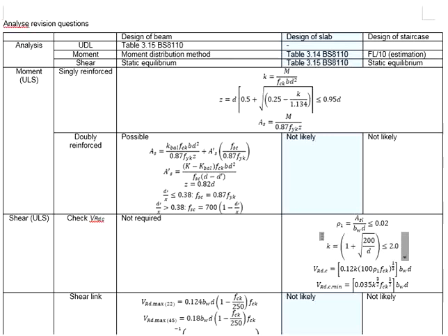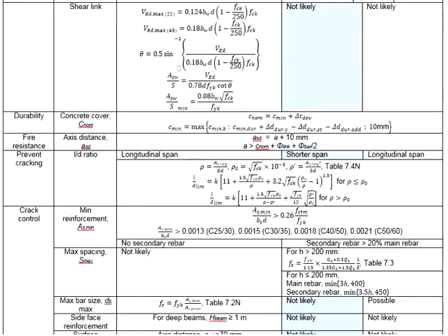Even there is no moment for the longer span of one-way slab and for the transverse directions of the staircase, you will still need to provide the secondary reinforcement bar. This is to prevent the cracking. And the secondary reinforcement bar is also used to keep the longitudinal reinforcement bar in position, as the main and the secondary reinforcement bar shall be tied together during construction.